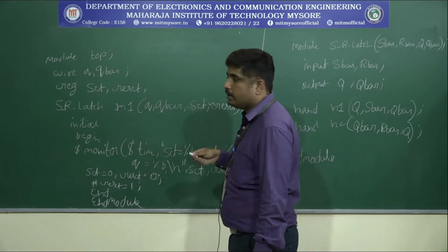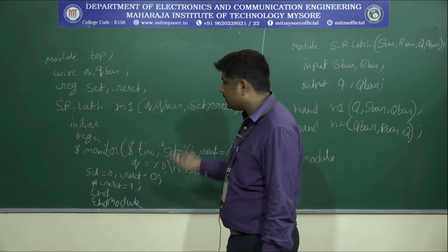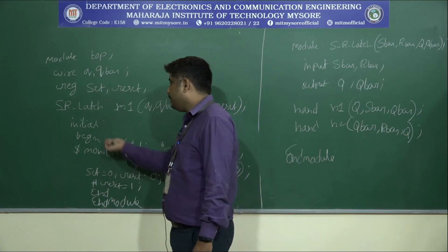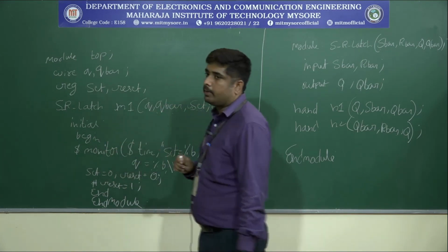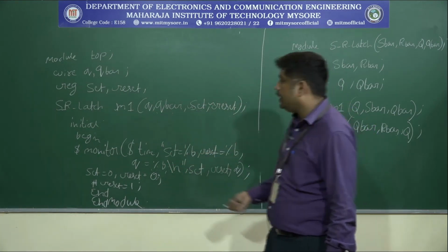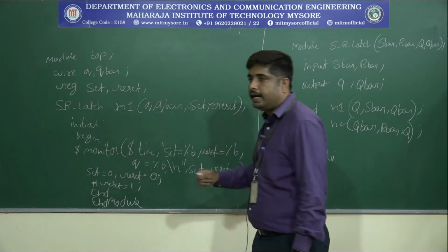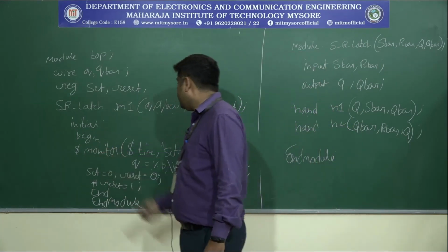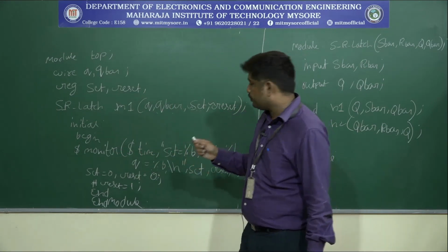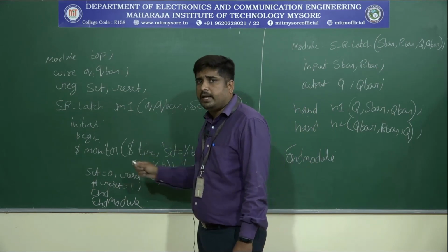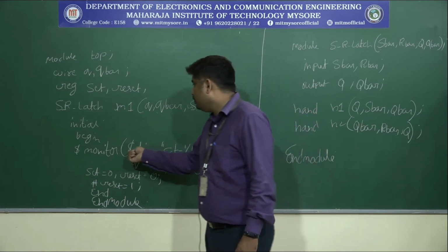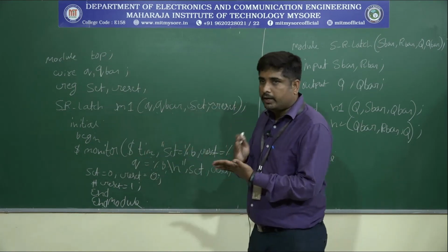Once it is done, next we have to put some data here. The data always starts with the keyword initial, then begin. Here $monitor. Why is $monitor required? We already discussed it in the previous session. It monitors the entire data, that's why we are using $monitor. Here $time indicates that we mention a particular simulation time. If it is simply time, it keeps running continuously. That's why you put $time, which indicates the particular simulation time.